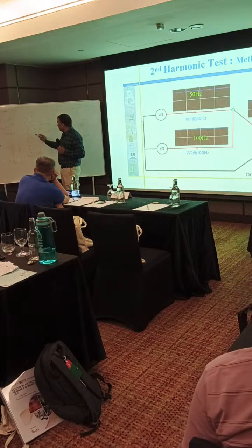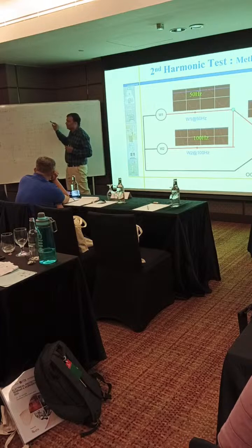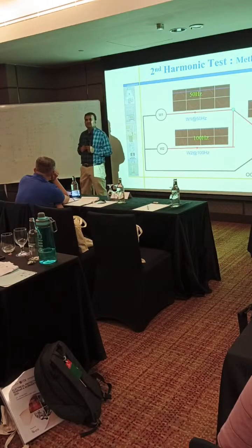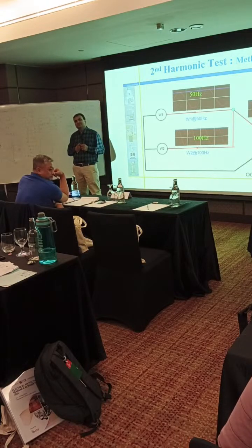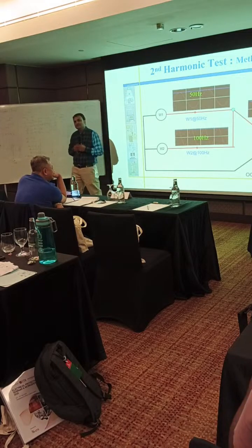What you have calculated is true in this case. Yeah, the second case, where the second harmonic component is injected through the second winding. The first case we usually don't follow, because for second harmonic we consider inrush at starting time. At starting time, on the secondary side we always consider no load condition.